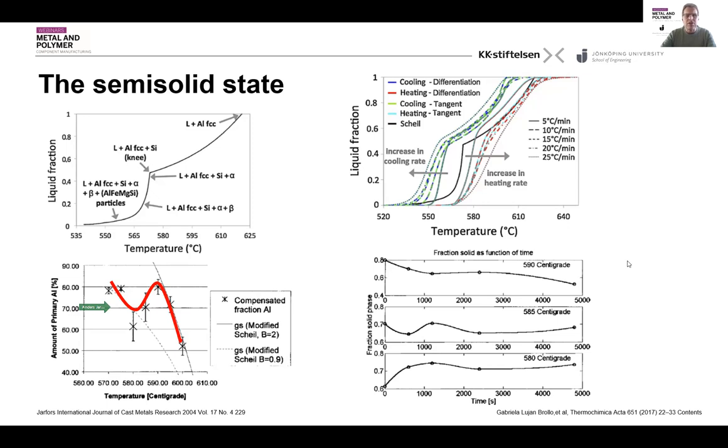And if you just in this intermediate, you sort of suffer a little bit for what you would call Le Chatelier instability, where you have a slight variation. Now, the time frame here is very important because you have to the left here a very short time. It's just going up in temperature and melting and quenching, so it's seconds, while these resolidification sequences are in seconds, so these are quite slow processes. So time frame of making the slurry is also very, very important.